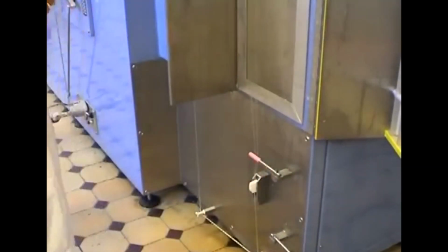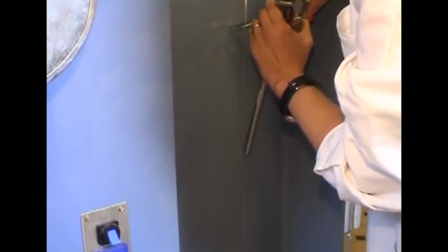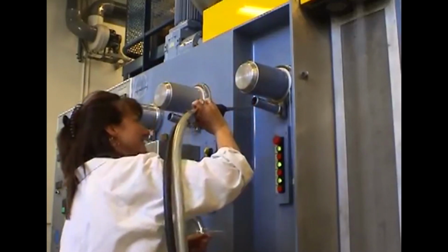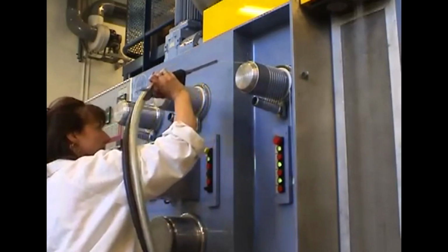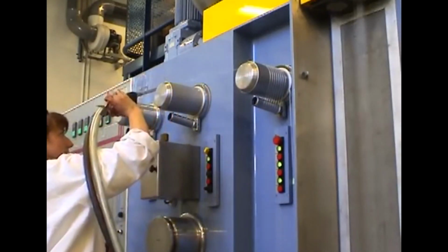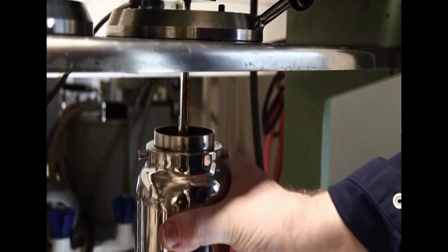Depending upon the type of polymer that is used and also the type of material that is present, whether it is a volatile solvent or a non-volatile solvent, the methods differ. Sometimes this chemical spinning is also called the extrusion method. That is, we have to make it into a solution and then it should be extruded through the spinneret. So, this is also called extrusion technology.